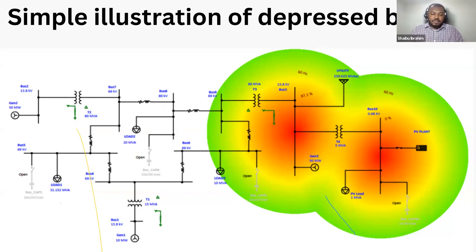So they would say, okay, if there's a problem, within 10 seconds, we want the voltage to reach 90% of the rated voltage. So 90% within 10 seconds. If there's a fault, within 10 seconds, the voltage has to rise up to 90% or 0.9 per unit. And then that is how we understand it. So you need to understand simulation and how to actually analyze this. This is a very important skill to have.